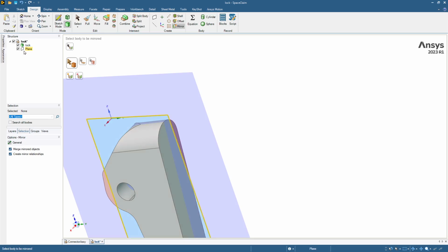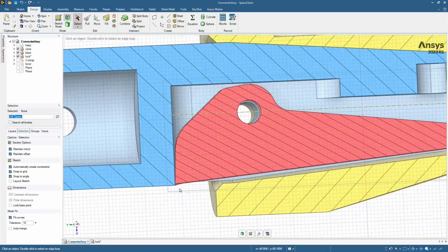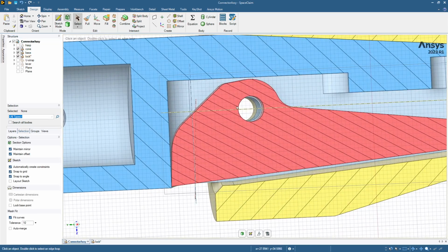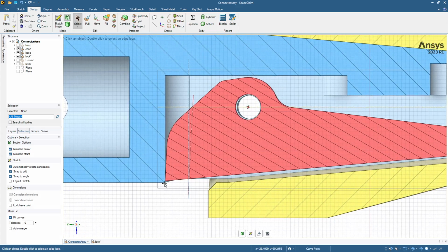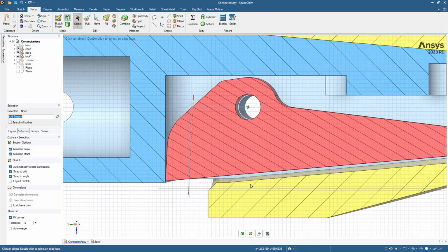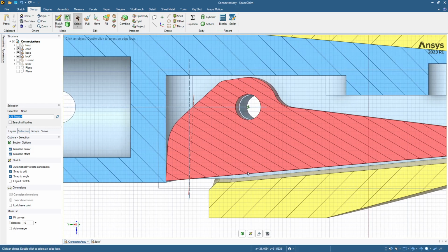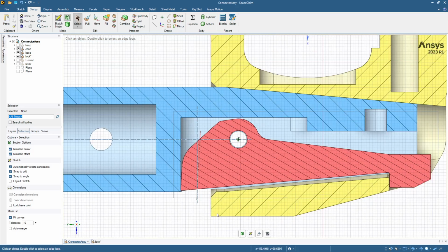And then in the assembly, what we can see is the contact point has now moved further away from the center hole, and so the same 0.2 millimeters of displacement is a larger lever arm from the pivot, and therefore there'll be less motion at the other end.